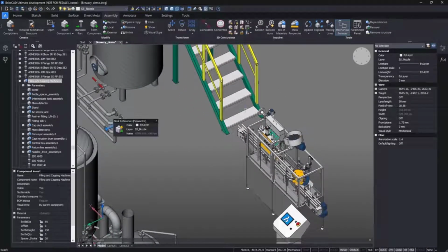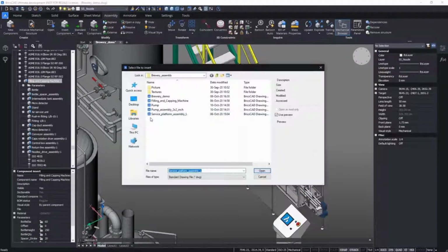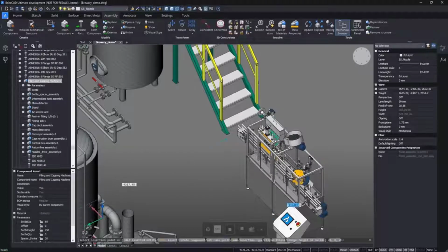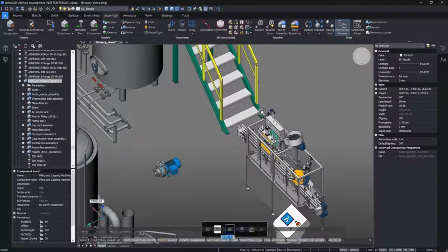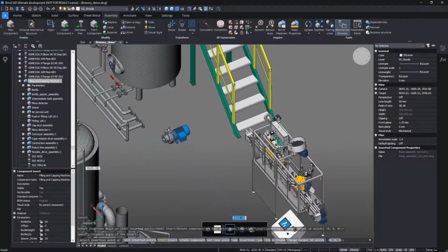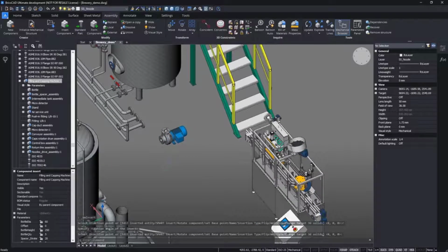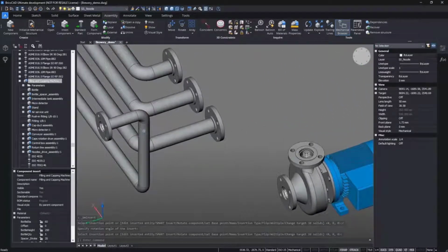But we cannot directly connect the filling line with the layout. We need to add a pump, which will transfer beer between them. We do not want to place the pump in front of the required flange because it will block the passage. So what we actually need is to place the pump behind our flange, but it again will cause some modification of the existing layout. Let's try to perform such modification and connect the layout with the filling line.